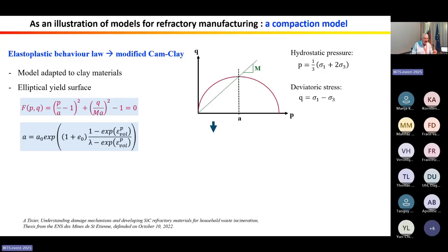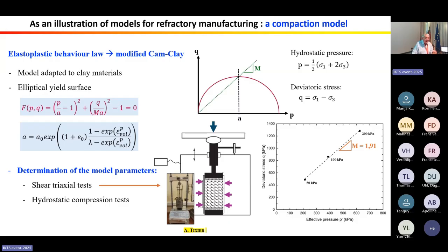This model is very well adapted to minerals and especially to clay materials, with an elliptical yield surface. We can define the hydrostatic pressure and the deviatoric stress, and we can determine the model parameters with two types of tests, shear triaxial test and hydrostatic compression test.